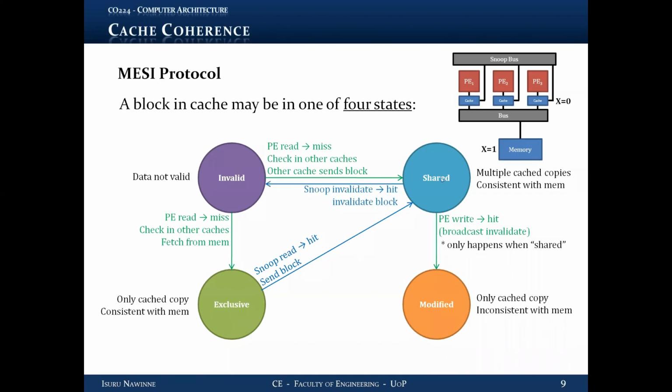The block there was shared. Since this is a write invalidate protocol, we see the snoop invalidation broadcast signal, and we have a hit. We had a copy. So cache 1 controller marks the copy as invalid. The copy is transitioning from shared to invalid, right?